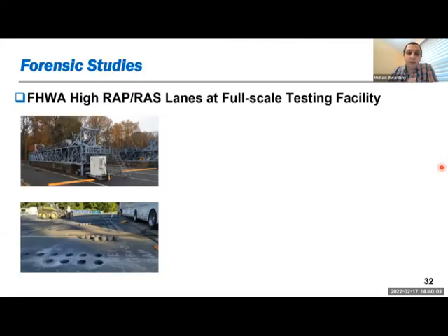For forensic studies, at FHWA, we have various sections with different recycled asphalt pavement and shingles, in high concentrations. And we load them with the accelerated load facility here. It's a full-scale experiment. We collected field cores, extracted the binder, and did some testing.